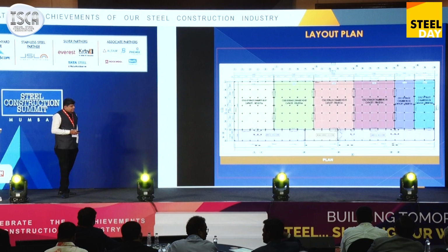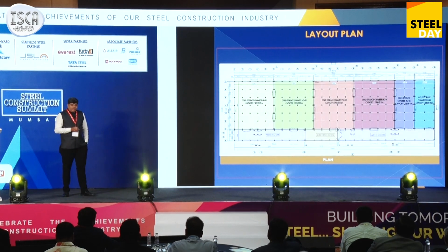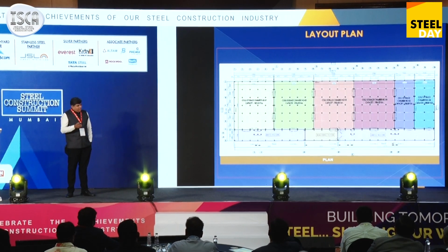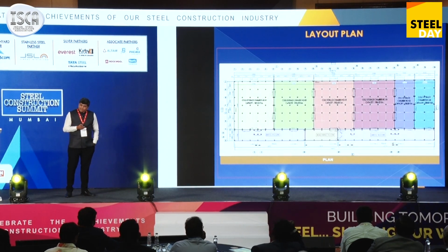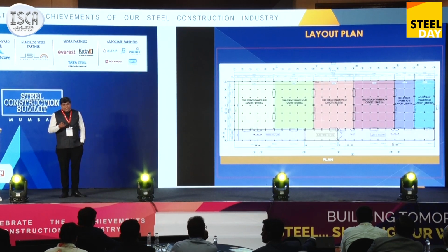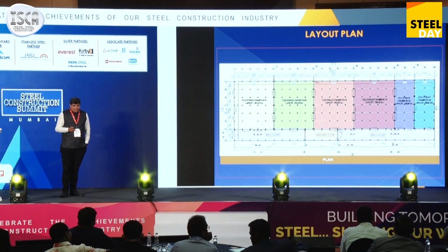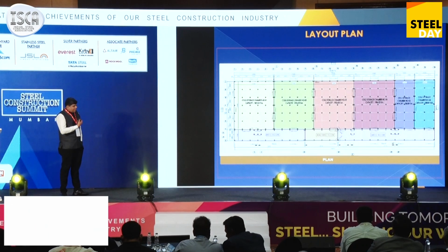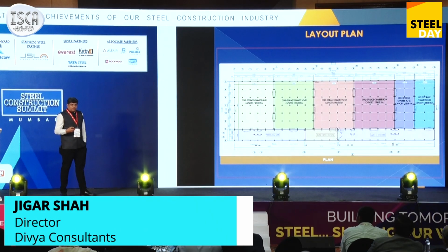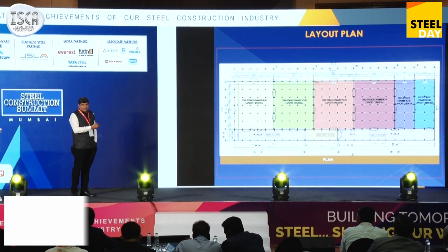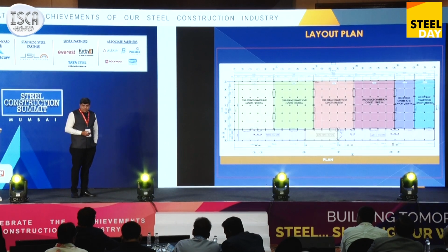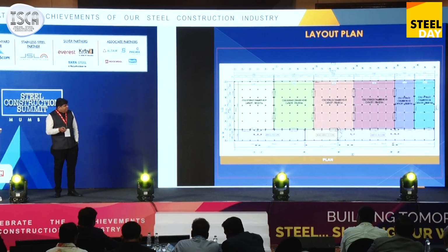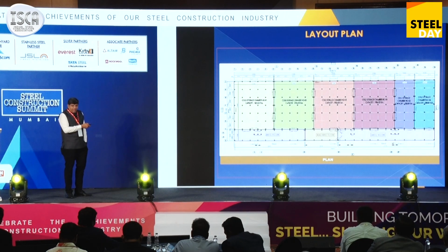This complete cold storage is divided into 6 chambers. The bigger chamber has a capacity of around 1900 metric tons, and the smaller is around 235. The purple zone is an ante room where material coming from the lift is kept, and from there they take it inside the cold storage. The orange one is the machine room, which is done in RCC.